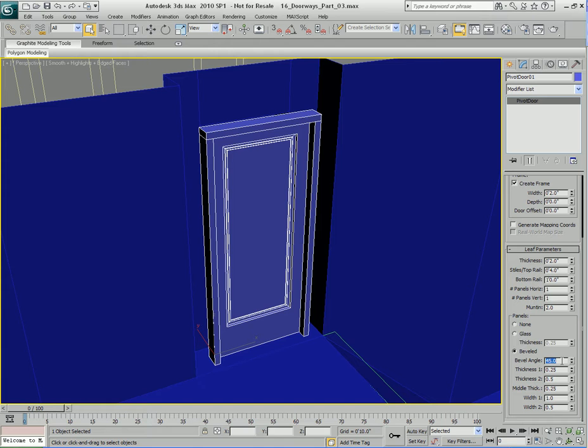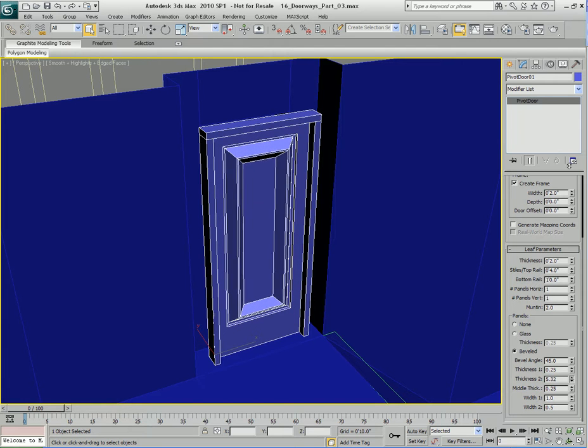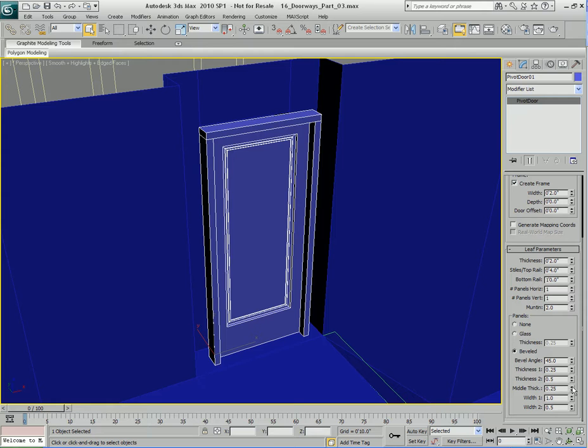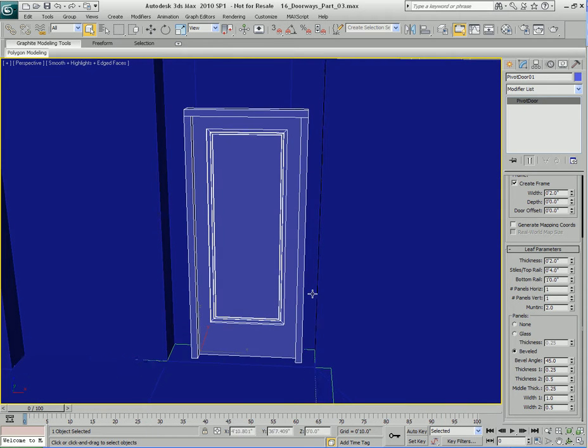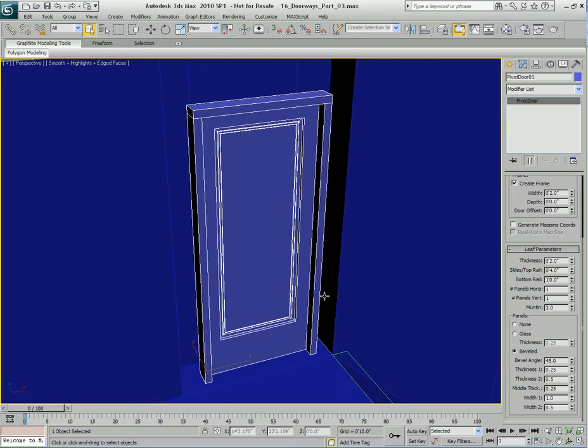And these are the default bevel parameters. So bevel angle of 45, you can always change that, as you can see. You have a thickness 1, which if you change that, you can see what happens. You have a thickness 2, which is going to make more adjustments to the door, etc. So I invite you to take a moment to experiment with these different parameters, which allow you to customize the look of your door and make all kinds of different looking doors. I'm just going to leave it alone like this because I'm going to say that I'm happy with the way the door looks right there.